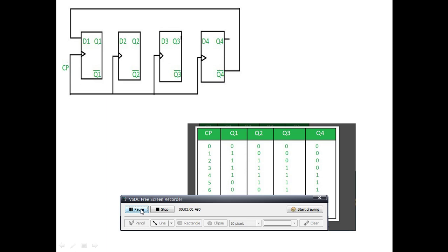Second flip-flop output is 0. Third flip-flop output is 0. Fourth output is also 0. But here this will become again the complement of 0, nothing but 1. So again, third clock, if you apply the third clock, what will happen? If we apply the third clock, this value will be shifted to the next value as shown in the figure.